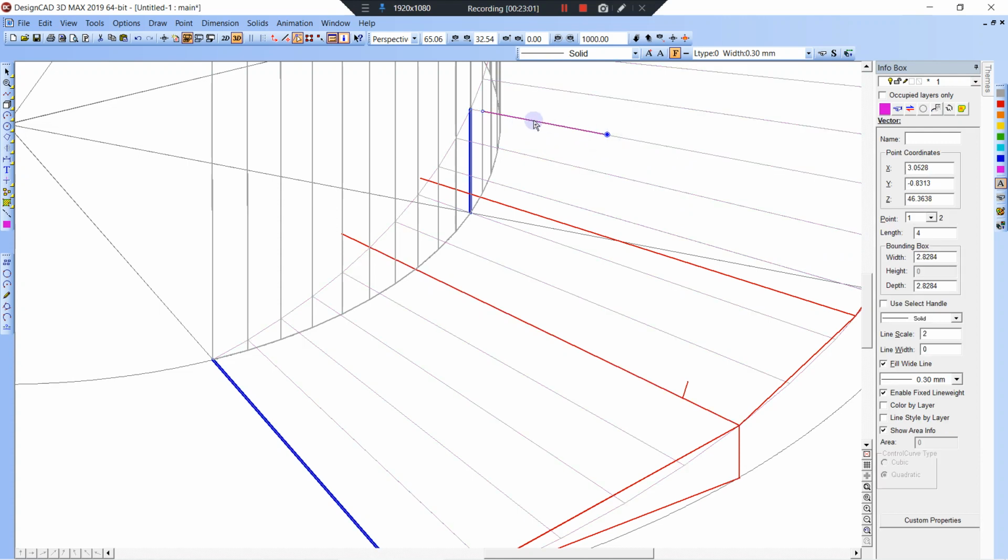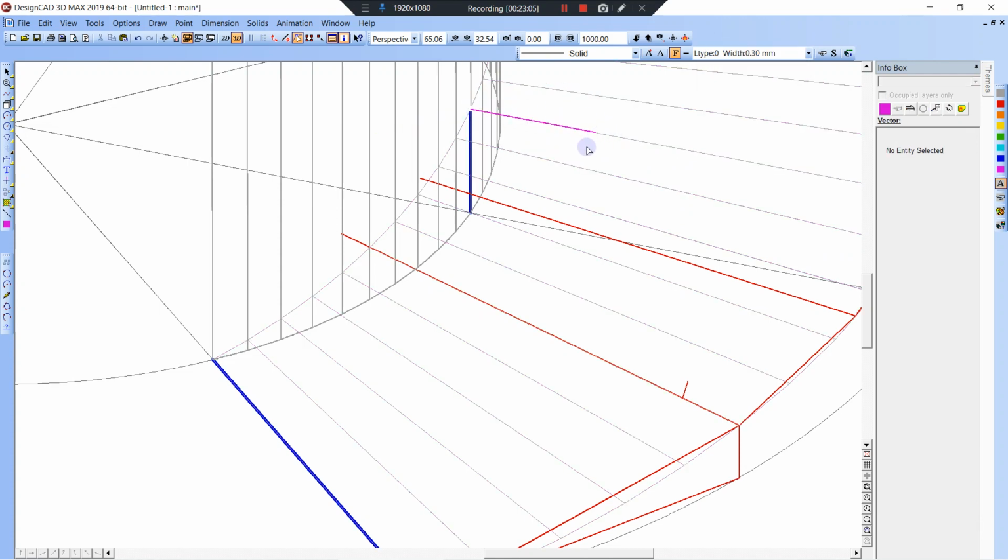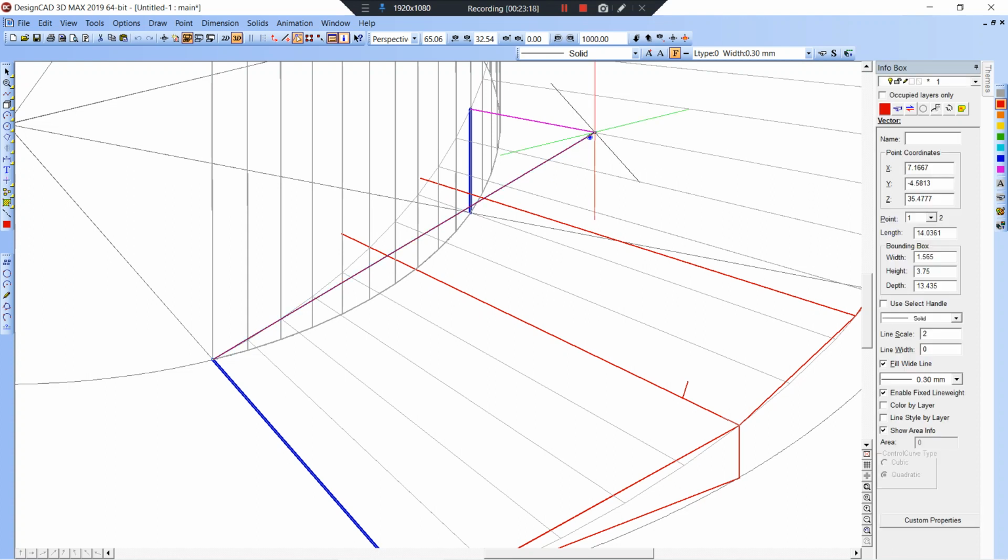So let's see, right here you can take your line V, your string line, pin it here, and then you come up here and hit it here, right? And you can take it and sweep it across that 4 foot level, and what'll happen is it'll hit these points as you sweep it.